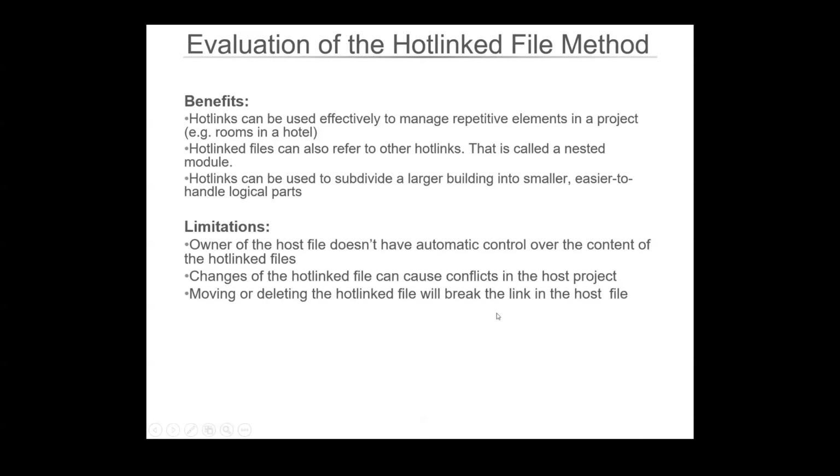So, limitations of this one: you can't change the hotlink file automatically in the main file, so you've always got to do that open separate ArchiCAD or open hotlink in separate ArchiCAD command, and then go and make the change. But generally, most hotlink files open up pretty quick, so it's a small sacrifice to make for having control over a lot of the project all at once. Sometimes it can cause conflicts, so we've just got to keep an eye on that.